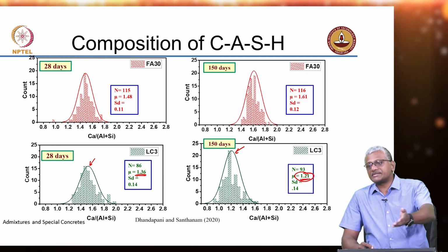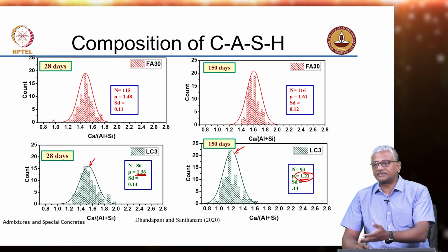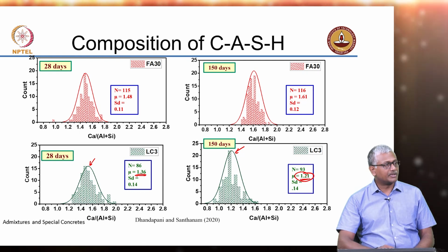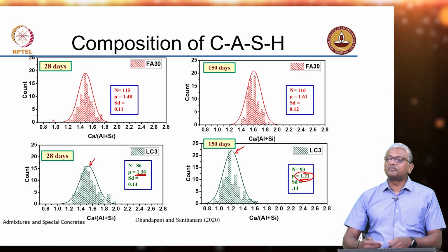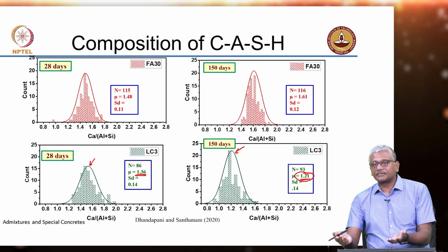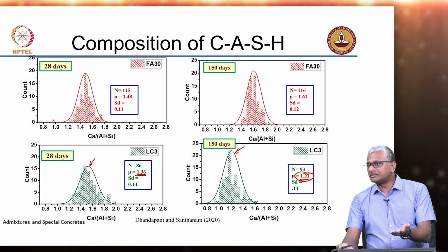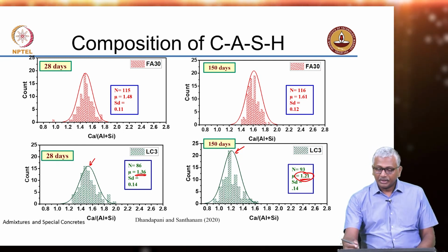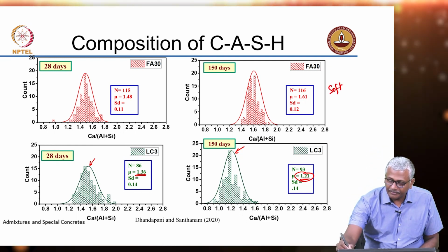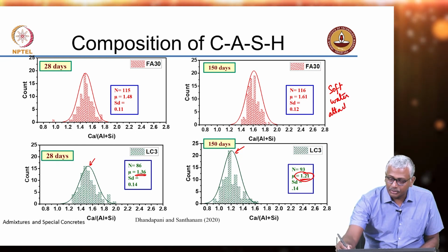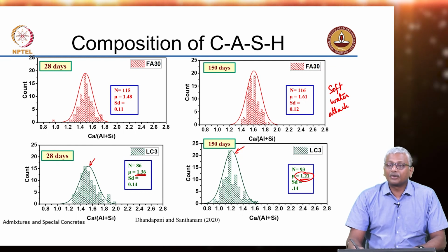Okay. So, the phases that can be dissolved early will be leaching out first. So, compared to CSH, your calcium hydroxide leaches out faster, much quicker removal of calcium hydroxide can happen in the system. So, even in the conditions of simple soft water, which is devoid of minerals, right, this can actually damage your concrete in the long run. So, people have reported soft water attack. Maybe hard to imagine, but soft water can also attack concrete.